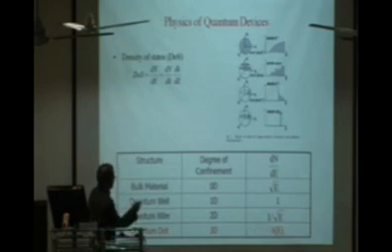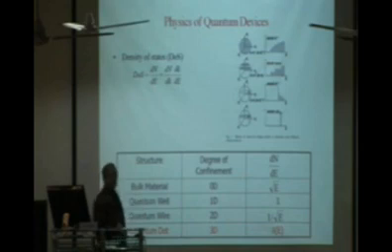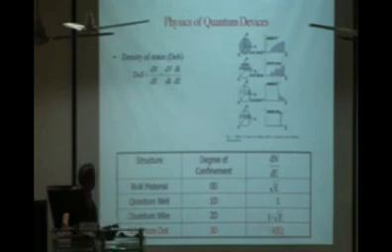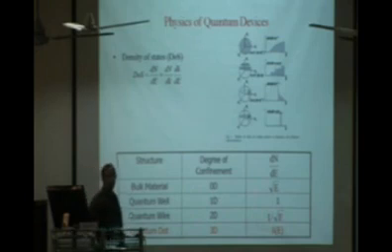As soon as you reduce the dimension and make it a 2-dimensional quantum well, it behaves like a staircase. In fact, the exact dependence has been plotted here. In the case of bulk material it is proportional to E to the power half, and in the case of a quantum well it is independent of the energy. It only goes to the next energy level. But for the same quantum number it is independent of energy, because this remains the same.